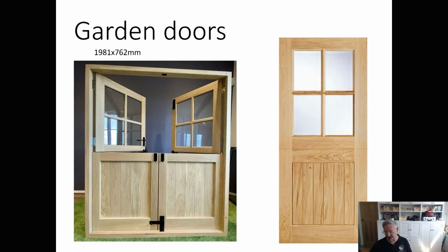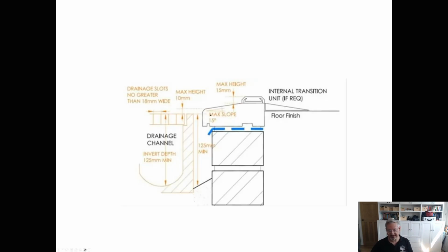So I'm going to buy these doors, build the frame round, and then take the doors away so the frame can stay there, all with diagonal bracing, so that we can build up to it, and we can drill into it, into the brick wall as we go, and it will help us keep everything level. And I want some sort of a sill, and the drainage channel here. That's the base door sill and the drainage channel, and the finished floor there.